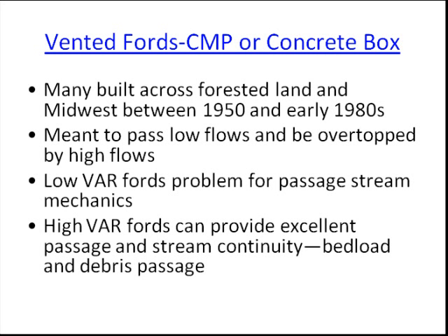All right, vented fords are found in many locations across the Midwest and eastern United States, and most were built between the 50s up to about the mid-80s. These fords commonly consist of multiple small culverts set at or near the stream bed level that were covered with backfill and commonly capped with concrete or asphalt to harden the embankments along the upstream and downstream sides.